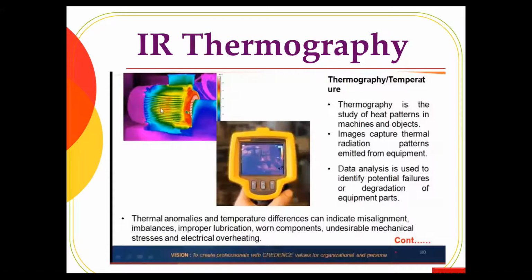Thermography is the study of heat patterns in a particular region, where the infrared radiation emitted from the machine surface is captured by the thermography camera. Then that pattern is displayed on the camera's display screen like a thermogram. What is a thermogram? That means a color palette with some hot spots, a hot line or a hot area in terms of a temperature scale. So next, please.